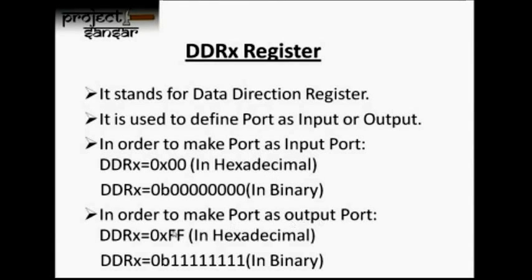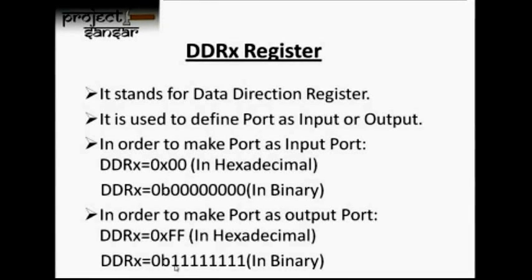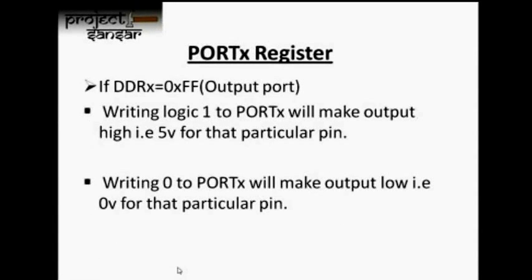If you want to make the port an output, you give the value as 1 for each pin. So it would be DDRB in hexadecimal 0xFF, or in binary DDRB 0B followed by 8 ones.